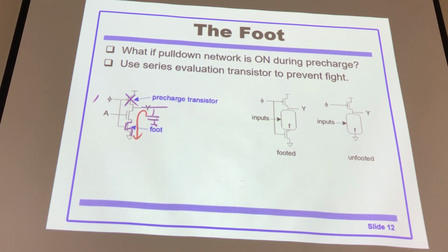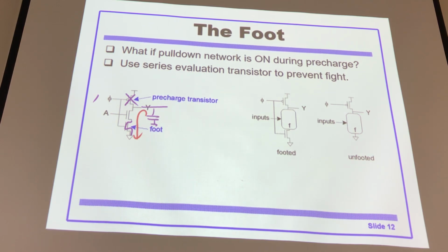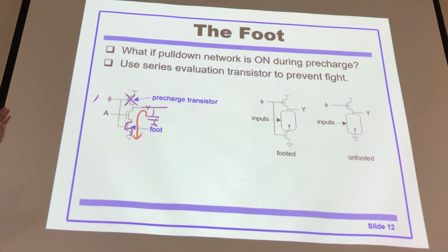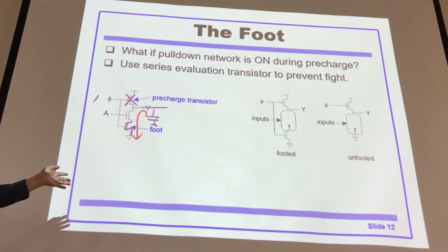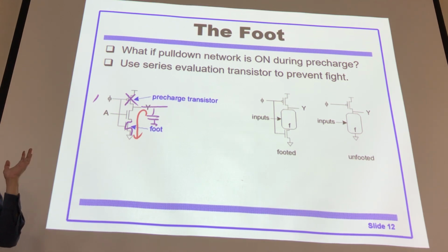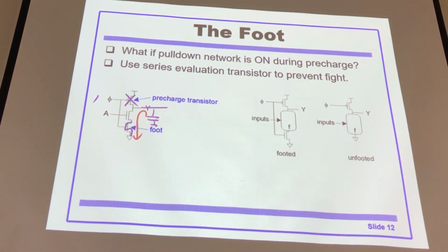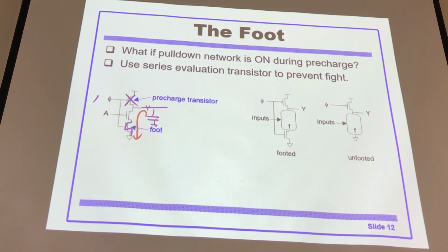Okay, it could be faster. It could be faster than static CMOS. Actually, dynamic circuit is popular for high-speed circuit design. For typical circuit design, static CMOS dominates the whole industry. However, for some high-speed circuits, people could use dynamic circuits.